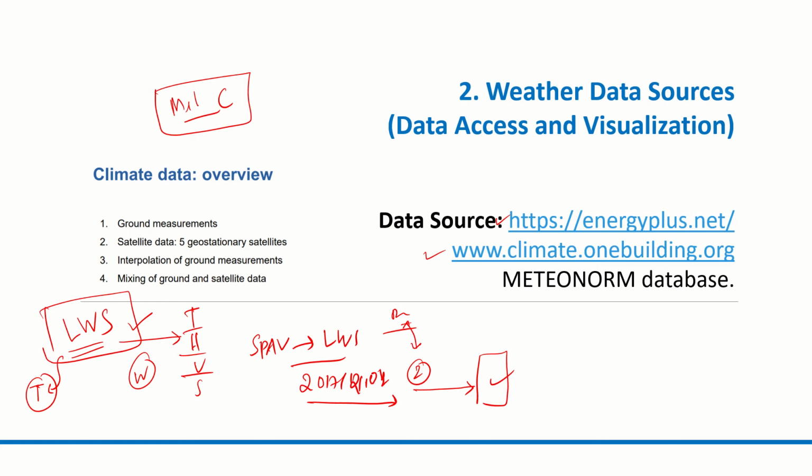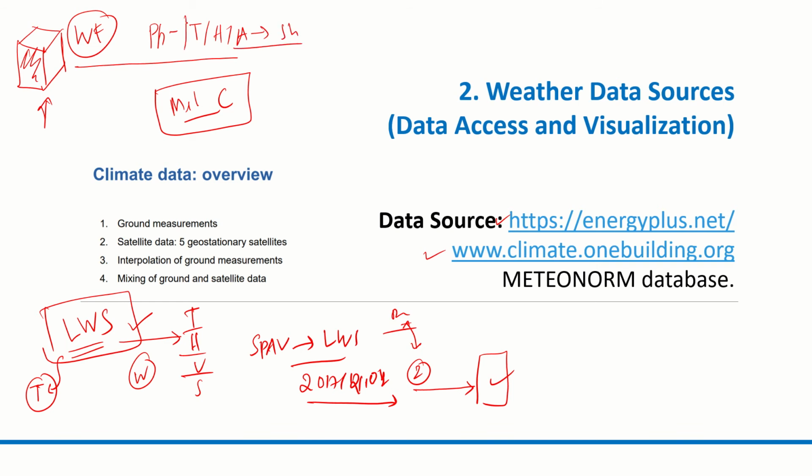For example, many times we use typical weather files for building energy assessment and so on. In addition to that, we also do some physical measurement. We take instruments and measure temperature, humidity, air velocity, solar exposure, insolation, whatever information we are trying to collect. We take some primary readings as well. Why do we do that? It is just to validate whether the simulations are right or not.